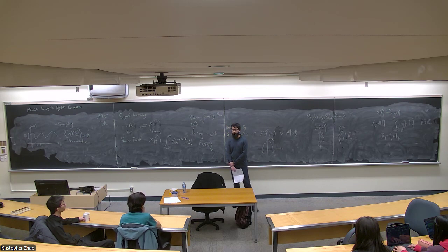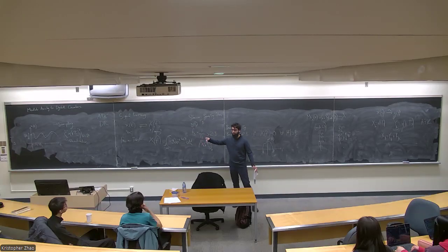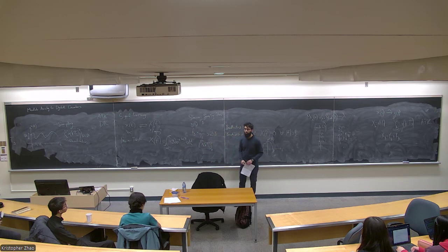Basically the reconstruction is normally done using what's called a sinc interpolation. That interpolation defines an infinite sum, so you have to compute an infinite sum in order to obtain the value. However, for large values of t, those terms often become very negligible, so having them or not having them in the sum doesn't really affect the quality too much.